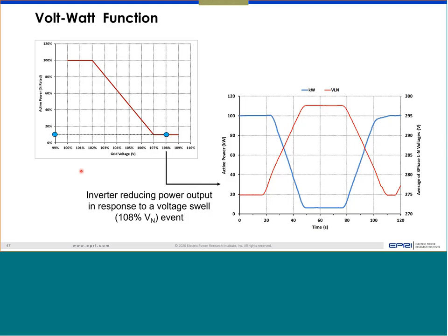However, right now we are doing a pilot project with one of the utilities. The utility intentionally wanted to see if the inverter can provide reactive power support during nighttime. At night, of course, there is no solar, no irradiance, but the manufacturer has to make some adjustments in the inverter operation. It has to be powered from the AC side, because during nighttime there is no DC power.